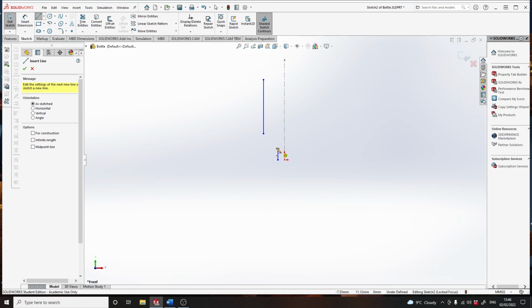And then I want to join these things up to make the curves on the bottle. Having practiced this a bit earlier, when you're making shells, one of the things you have to be careful of is that SolidWorks won't do a revolved shell if the surface actually touches the axis of revolution. So when I connect this up, I'm just going to leave a little gap there, and then SolidWorks won't throw a wobbly, and it will do a shell for me. Okay, so those lines are good.